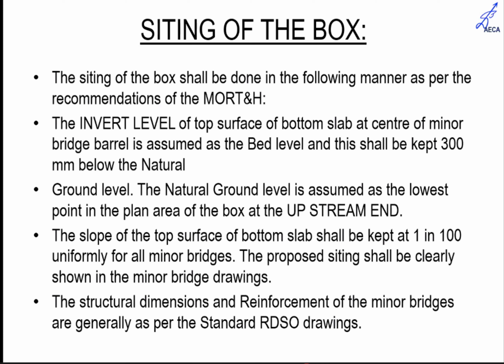So with this, the invert level of the bridge is below the natural ground level, which is the lowest point in the plan area of the box at the upstream end. So the hydraulic communication from downstream to upstream side is precluded by adopting this approach.